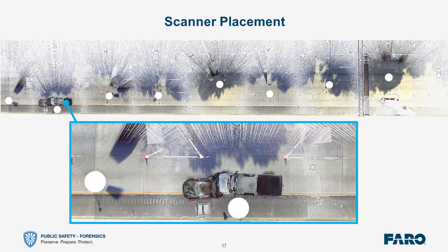Another quick question here that I want to combine, because I think they're two portions of the same type of question, and it deals with scanner placement and sphere placement. Ryan wants to know, when establishing the plan, how much space should be used between spheres if the investigator determines that's the best way to target our scene? I'd like to go back to that a little later on, but the quick answer is that the distance between the scanner and the spheres is determined by the resolution you're scanning at. The higher the resolution, the further away that sphere can be. Obviously, the closer the sphere is, the lower the resolution you can use. But you do need to make sure that the scanner is capturing enough of that sphere for there to be a lock on it. The software needs to recognize it. We'll go into that a little more later on.